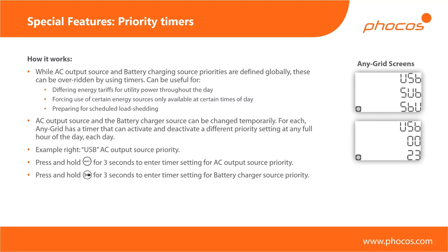And I think that the most common scenario will be when people have different power tariffs throughout the day. So again, my example from the very beginning of the session, in some countries in the middle of the day, when actually there's not a high demand for power, but there's a lot of production, there's a lot of PV systems which are injecting to the grid. So the power can be very cheap then. So here you can say, okay, let's say from 11 o'clock in the morning to 1 o'clock p.m., I want to automatically charge my battery from the grid because, well, if my battery is not full at that time, energy is so cheap, I really want to have that energy for later because then it can get through the night, because maybe my battery is a little bit undersized.